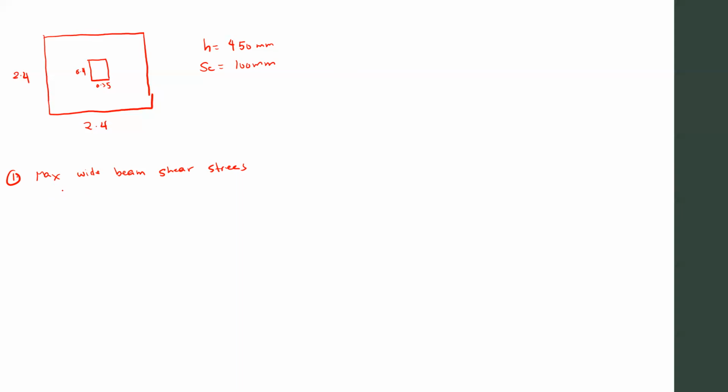To determine the effective depth, ito yung total H, okay, total H minus the steel cover. If you recall how to determine the effective depth in your reinforced concrete design. So this is 350 millimeter. Okay? Then after that, pwede na natin sukatin yung D distance from the face of the column.